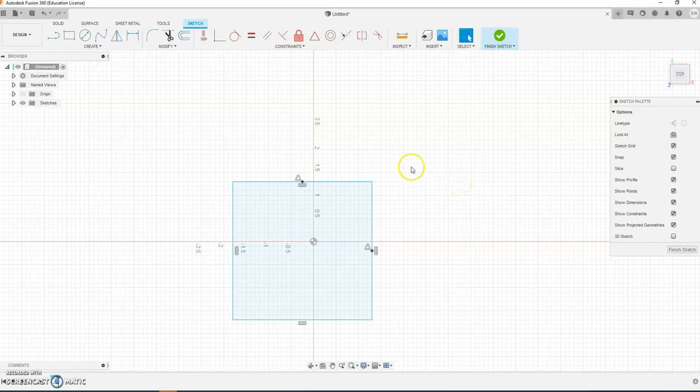And now I'm going to go to my next part. My next part is actually centering this block up. That was kind of the previous step we needed to do to center this. And to do that, we're going to come up to this area that says Constraints. Some of these up in the constraints should look somewhat familiar. This one here is tangent. We know what tangent is. We've seen that symbol before.